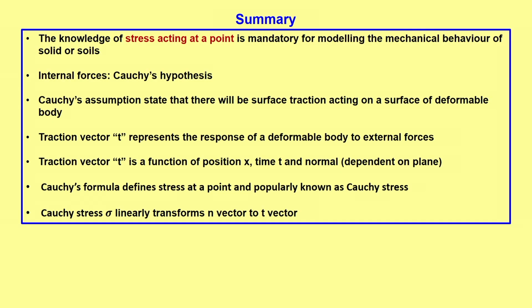The traction vector T represents the response of a deformable body to external forces. The traction vector T is a function of position x, time t and normal n, dependent on plane, and Cauchy's formula defines stress at a point, popularly known as Cauchy's stress. Cauchy's stress sigma linearly transforms the n vector to the T vector. So, this is the summary of whatever we have seen till now.